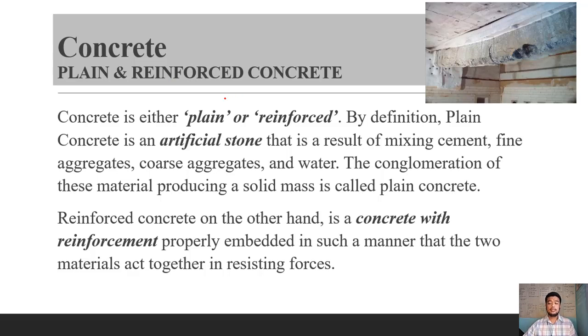So what is concrete? Concrete is either plain or reinforced. By definition, plain concrete is an artificial stone that is a result of mixing cement. Okay, cement is the powder. We also have fine aggregates, which we commonly call sand, and coarse aggregates, your gravel.